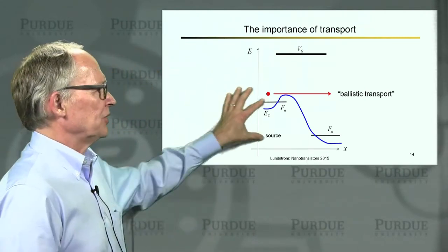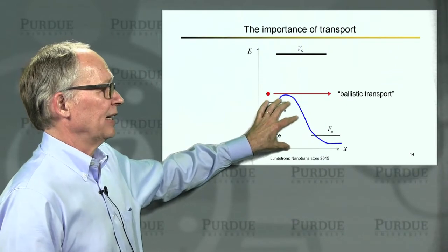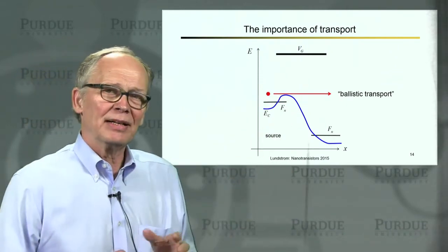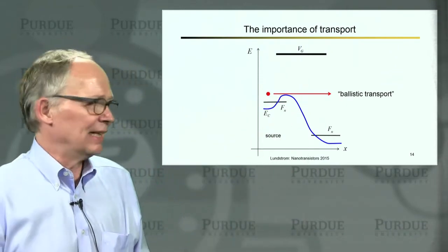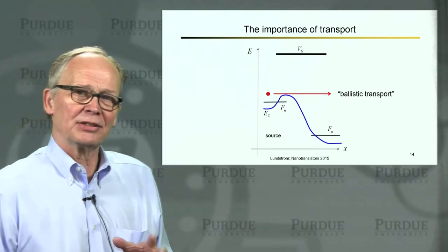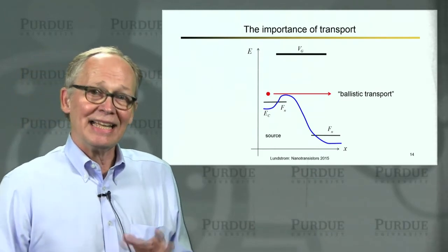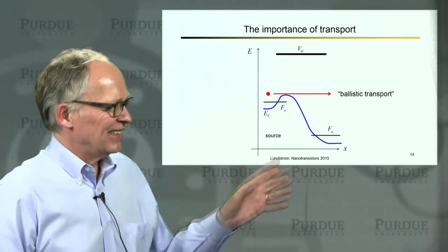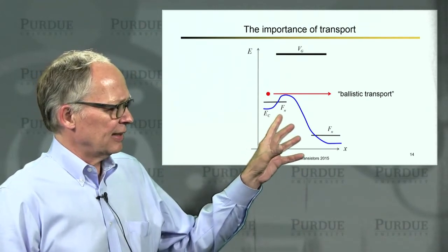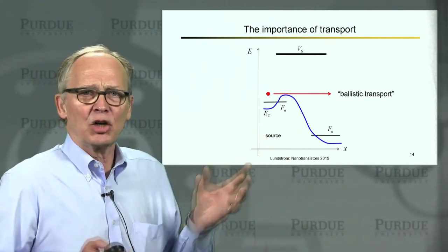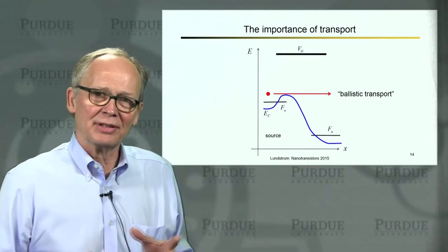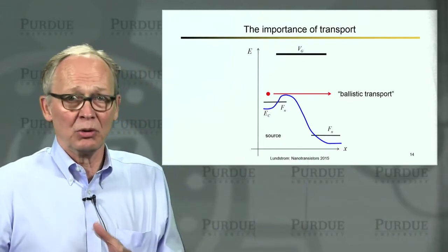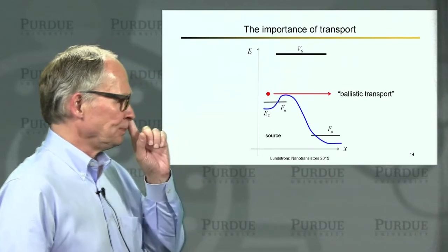Well, part of the course is about electrostatics, exactly how we control these barriers in a way that the transistor has good characteristics. That's MOS electrostatics. These sketches of the energy band diagram are a qualitative description of the MOS electrostatics, and we'll spend a whole unit on MOS electrostatics.